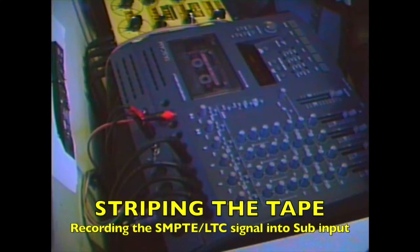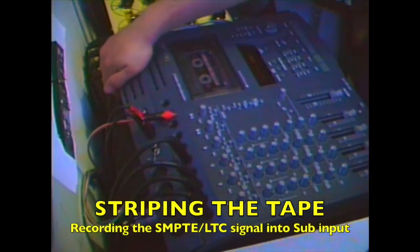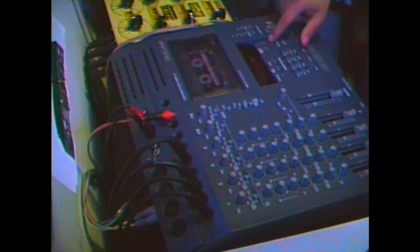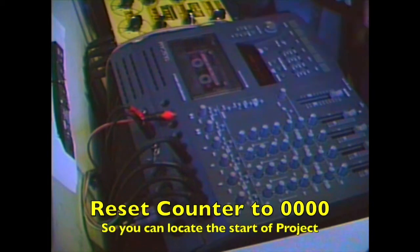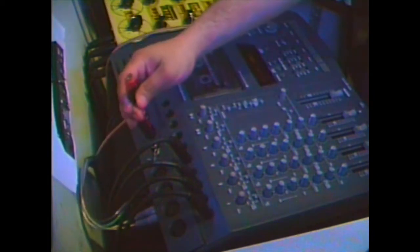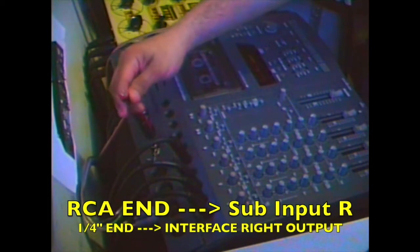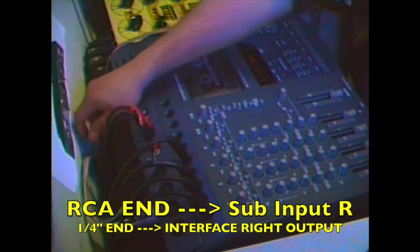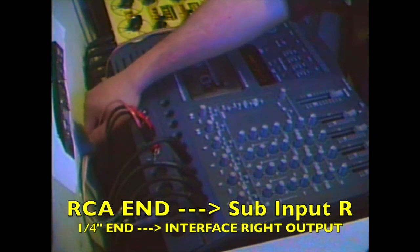Now that this is ready to go, we will move on to our PortaStudio. Just like in my previous video, all you have to do is arm your PortaStudio to record. Make sure you reset your counter from the point you want to start. Take the RCA end of your RCA to 1/4 inch cable, plug that into the sub input of your Tascam PortaStudio, and the 1/4 inch end is going to go into your line output of your interface.